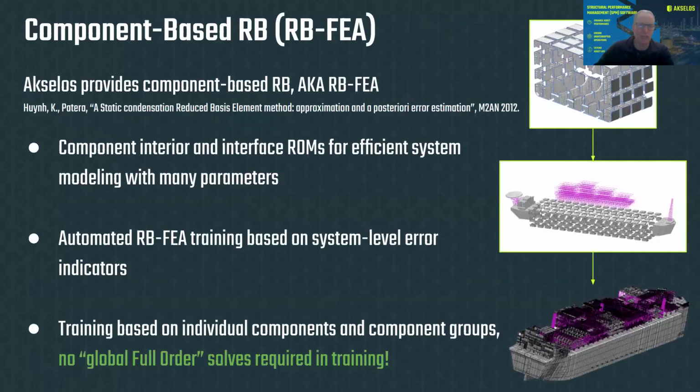So what we do at Akselos is we go to component-based reduced basis, or what we refer to commercially as RBFEA. And again, there are papers on this you can look up if you're interested. The key idea is we have component interior and interface reduced order models for efficient modeling with many parameters. So we make reduced order models on the component interfaces and on the component interiors.